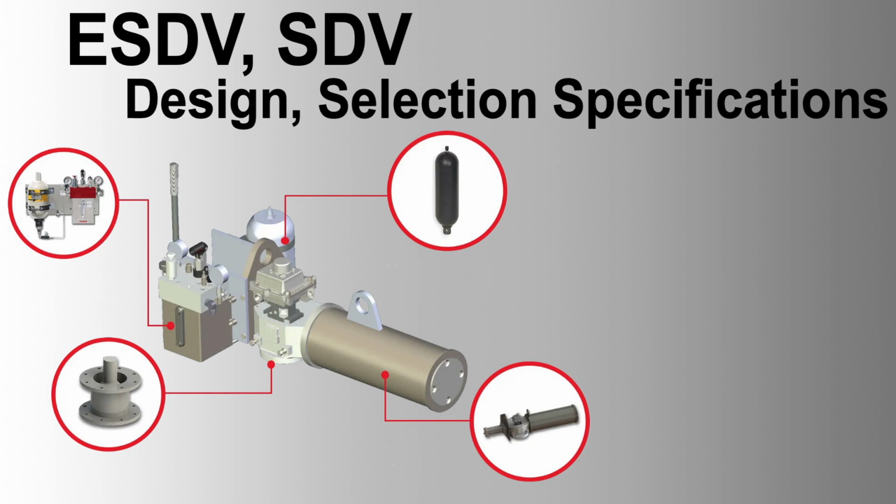Filter regulators: type self-draining automatic SS316L with a 40mm filter element. Air filters must have an automatic water drain and a 25mm mesh size. Limit switches, type: must operate on the proximity principle per DIN 19234, SPDT switches, intrinsically safe EEx ia. Enclosure: protection box with EEx e certified junction box. Indication: must indicate open-close positions and be connected to the PCS for operational monitoring with alarms.